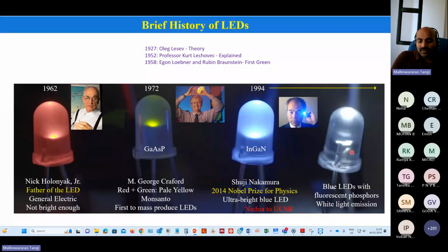As I discussed, though he achieved high quality gallium nitride crystals, he had problems doping them. Though he got N-type material, it was difficult to grow magnesium doped P-type gallium nitride. Then, by post-annealing and hydrogen passivation methods, he eventually achieved P-type gallium nitride as well. And the first InGaN blue LED he made out of this group 3 nitride system was highly efficient as compared to all the LEDs found by that time.